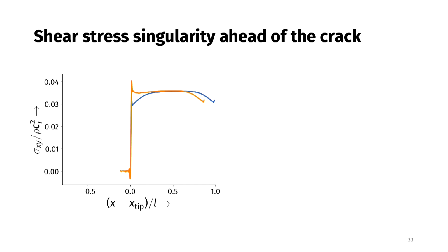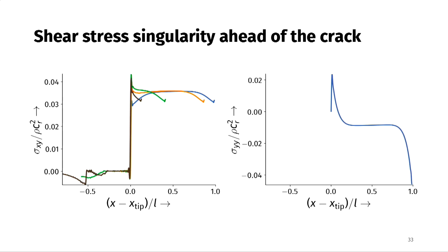And you look at the shear stress. The shear stress builds up as a function of time. These colors are all at different snapshots of time, and you see that it remains high. The normal stress falls off again for a dynamic crack moving like that. Right? This is consistent with what you would expect for a dynamically moving shear crack at the interface.